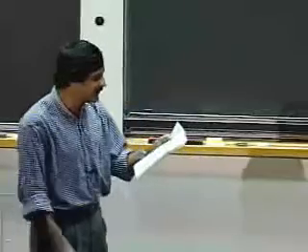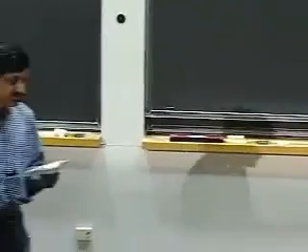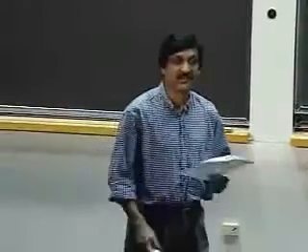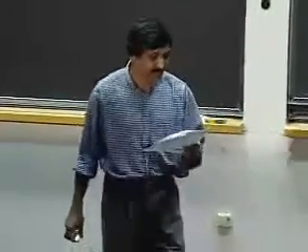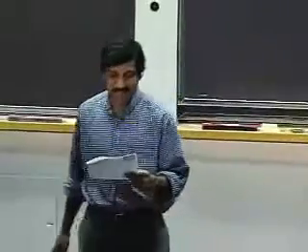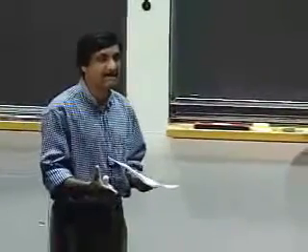The second thing I've circled is something called power dissipation. Power dissipation is said to be 0.006 microwatts per megahertz per gate. So it says power dissipation is 6 nanowatts per megahertz per gate.